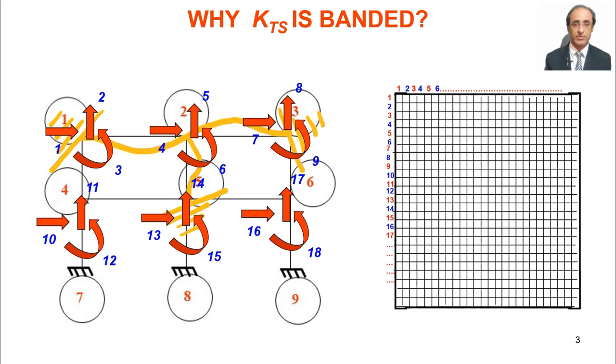So we have applied here this unit rotation, and which forces or which kind of moments they are generated. Let's say this is the 6th column. So now what will be K66? K66 has a positive value, so we mark here a tick. Now what will be other terms? K76, will it be there? Where is the 7th degree of freedom? It will have some value? 0.